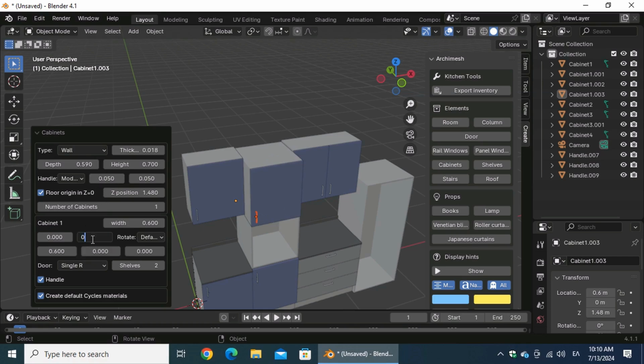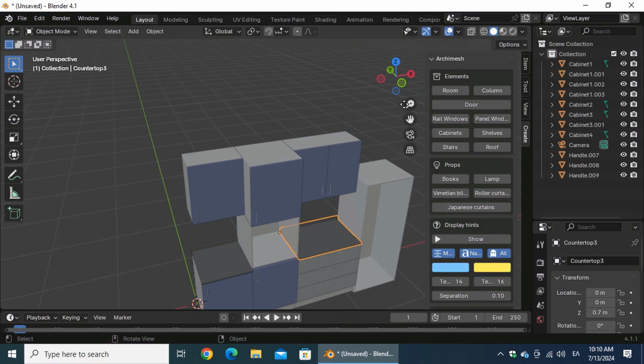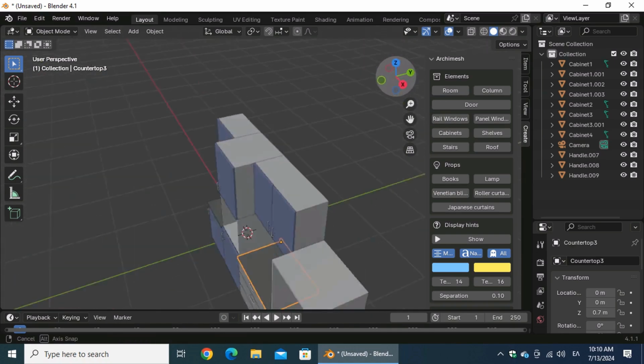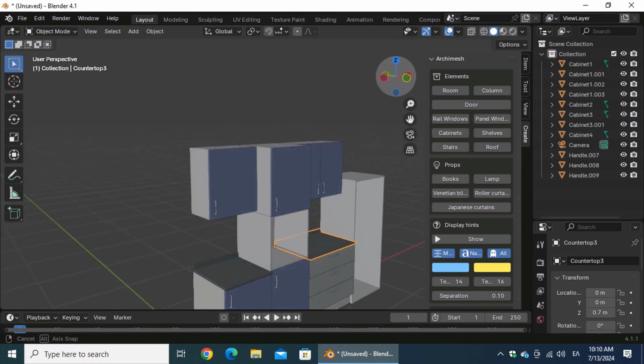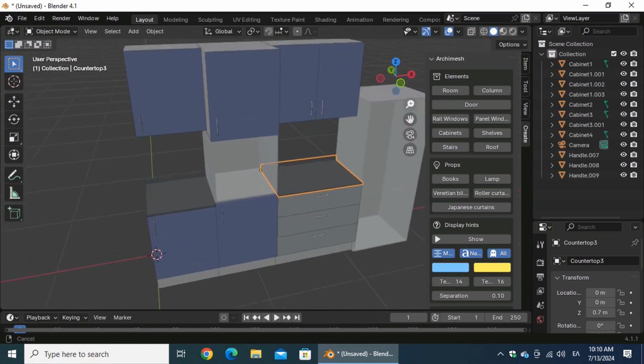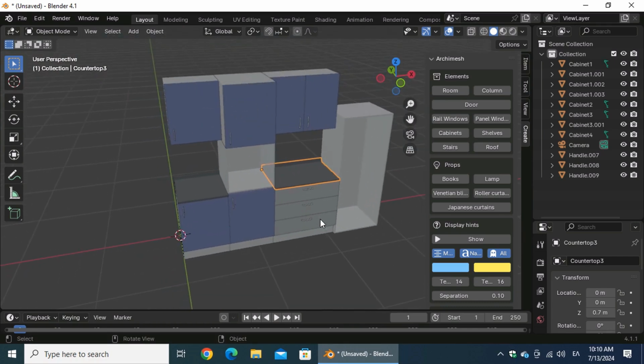Since the elevation of the newly inserted cabinet is 2 centimeters lower than the other wall cabinets, adjust the modify height size to 0.02 meters. Select an element in the viewport to apply the changes. Above the fridge, we'll add a cabinet with a depth of 59 centimeters to align with the top of the other wall cabinets.